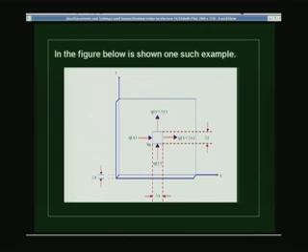And then you could ask the question: what is the steady state solution of the temperatures? That is, you want to know the temperature profile in this slab at steady state, that is, when the temperature is not changing with respect to time. To begin with, it will change with time. So to start with, let us say you keep it at 100 degrees on this side and 0 degrees on this side, and then there is a flow of heat, so initially there will be a change of temperature in this region, and after some time it reaches a steady state, and you want to know what the steady state temperature distribution in this area is.